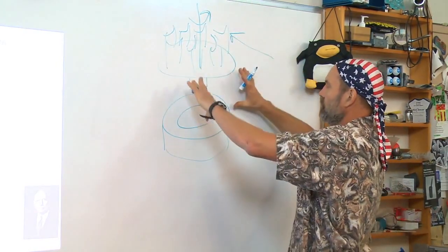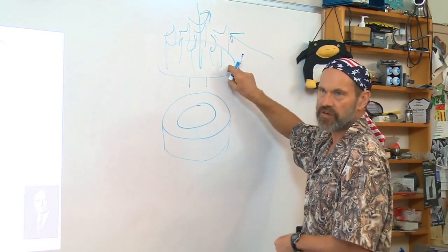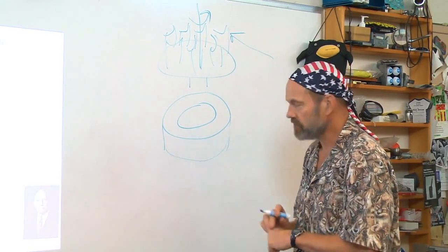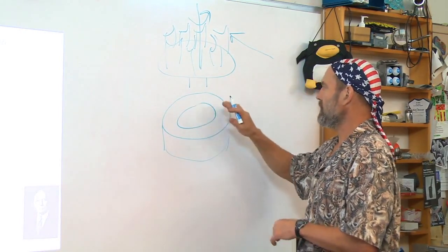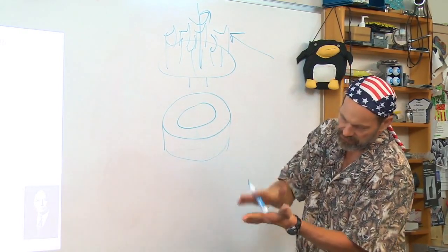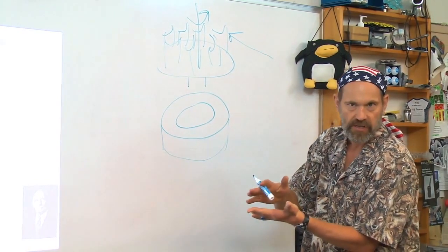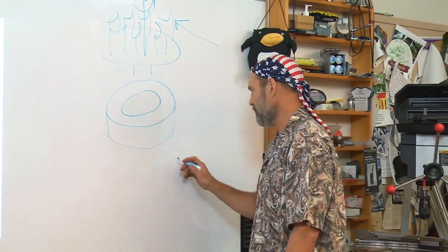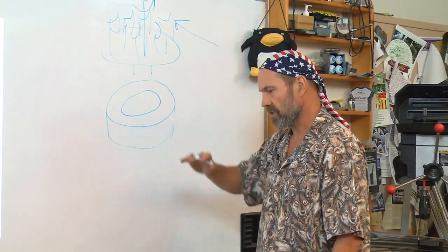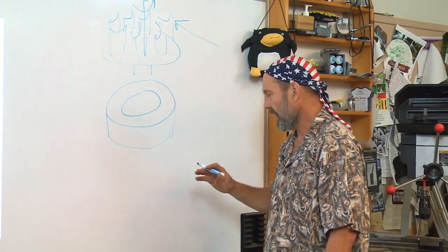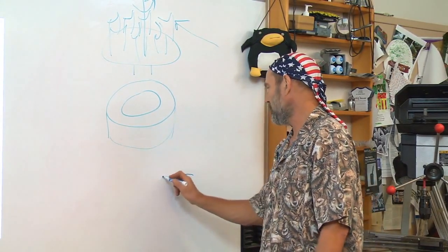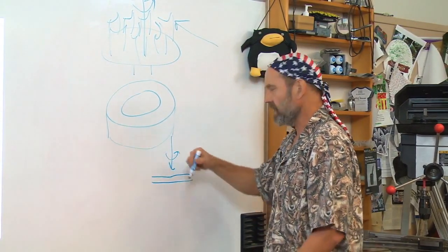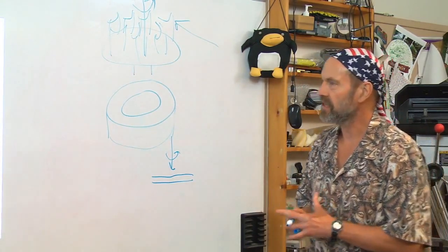There's a huge thrust load from the weight of the structure, and in some turbines, axial flow turbines, you would have huge axial loads. Well, to make two plates perfectly flat that'll fit together and not have a high point somewhere, such that you can have a hydrodynamic bearing, is very difficult. It's also very difficult to imagine that if I want to resist a very high thrust load, how do I do that between this surface and this surface when I'm pushing down and spinning? Where does the hydrodynamic wedge build up, like we showed in this picture?